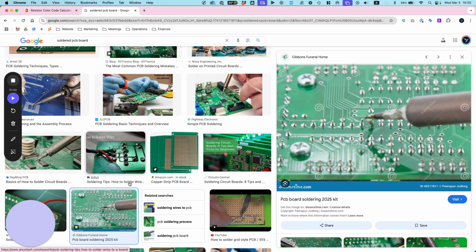Okay, let's take a look at your drone here. So it's no P's on this battery, just a straight 12S. I'm not going to draw out the individual cells, but let me just do it. 1, 2, 3, 4, 5, 6, 7, 8, 9, 10, 11, 12. Wow, that's a lot. Okay, if it's 12 cells, 44.4 volts divided by 12 cells is what per cell?